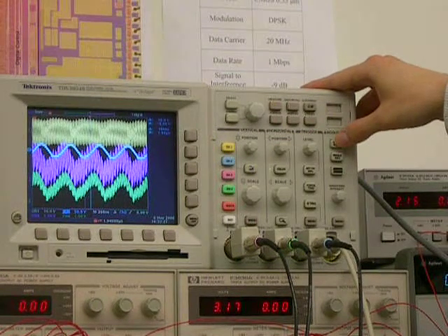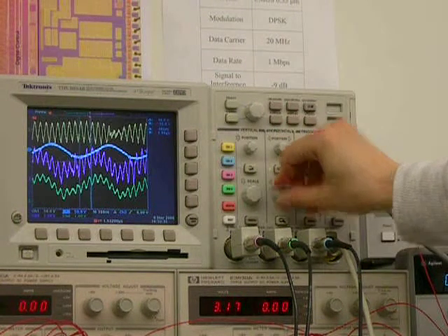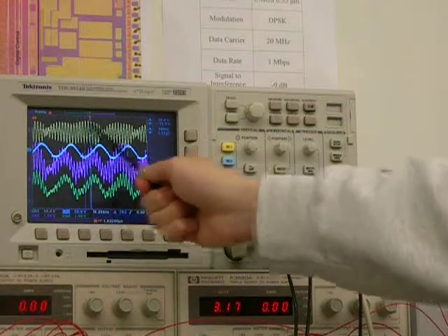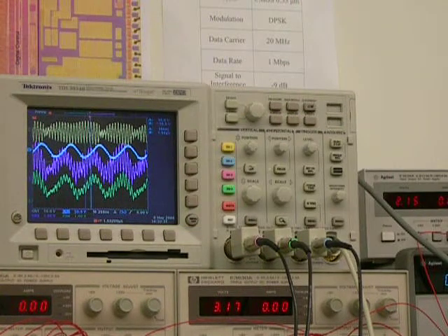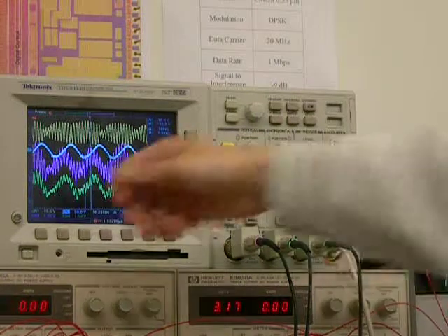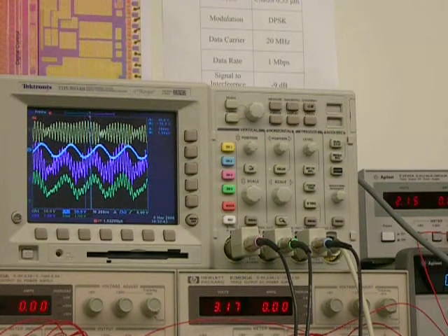There's one more interesting thing I want to show here. It's the sudden jolt that happens every so often. The reason we have these sudden jolts on the transmitted signal is that we create a transition edge on the PSK transmitter. By doing so, we're shifting the phase of the data carrier by 180 degrees.